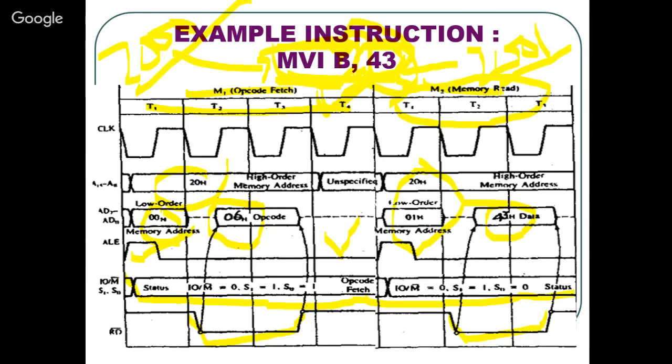So in total there are two machine cycles, meaning two different operations to complete an instruction. The instruction cycle is the whole from T1 to T7, with machine cycles M1 and M2, and a total of 7 time states. I think this session will help you understand the basic concept of the timing diagram. In the following sessions, I'll cover the timing diagrams of typical instructions of the 8085. Thank you.